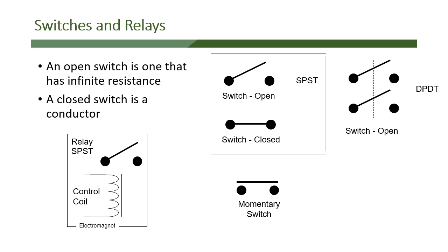These are called relays. There are solid state relays, mechanical relays, reed relays, different types of relays. But what are they for? Well, one thing they can do is handle huge amounts of current, 10, 20, 30, hundreds of amps, with big contacts that are very dangerous to handle. They can create some very high sparking when the contacts come in close contact with each other as it's closing. So we use a voltage to control that switch so that we are not in an unsafe condition if we had to throw it manually.